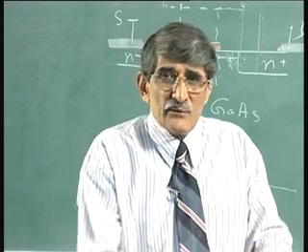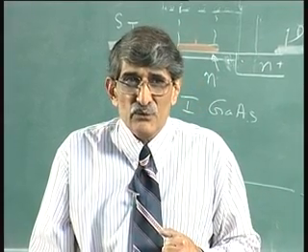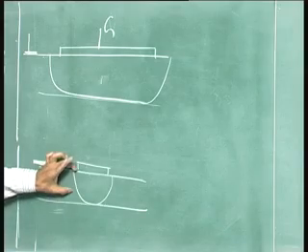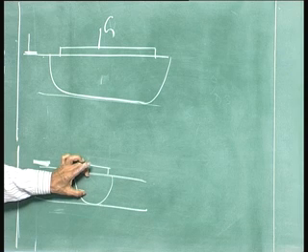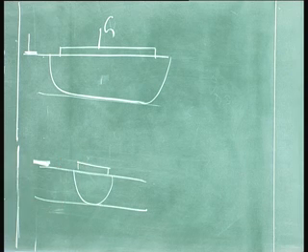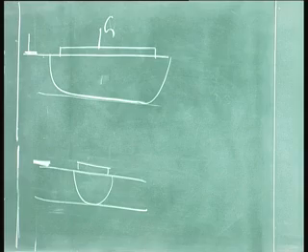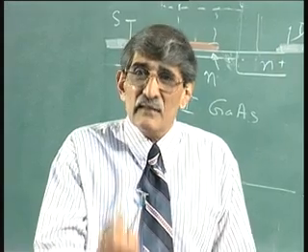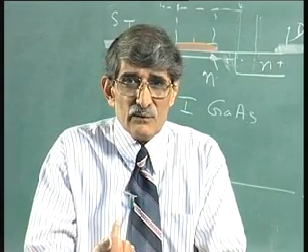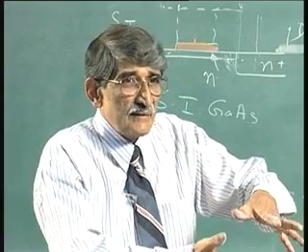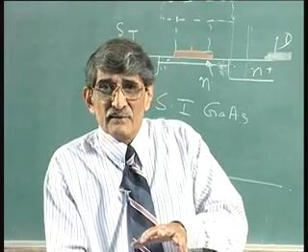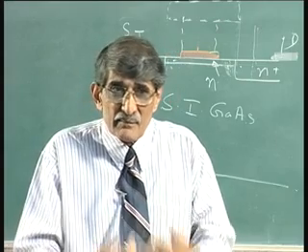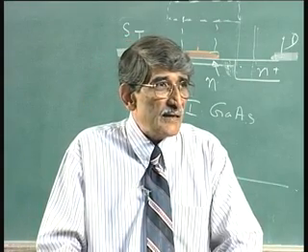Now, the two dimensional effect, how do you reduce it? This you are able to do because you reduce the thickness so that there is a flat portion. Flat portion decides your threshold voltage, but in the thing that we are discussing, the only way for you is to ensure that the field in the vertical direction is still large compared to the lateral field. See, the whole thing shifts in the depletion layer towards the drain, a distortion in the electric field and the depletion layer edge has come about because of the lateral field becoming comparable to the vertical field.